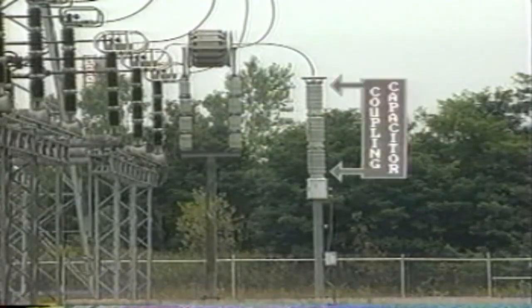We have discussed how to confine our carrier signal to the power line. And let's now see how this low power carrier signal, say 10 watts, is injected into the high voltage power line conductor. The coupling capacitor, abbreviated as CC, provides the means for power line carrier coupling.